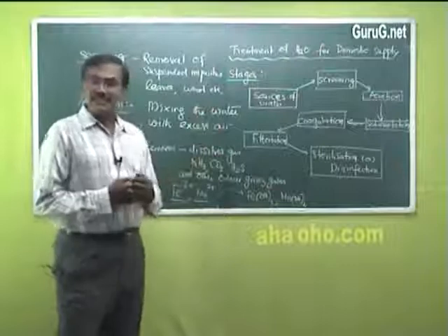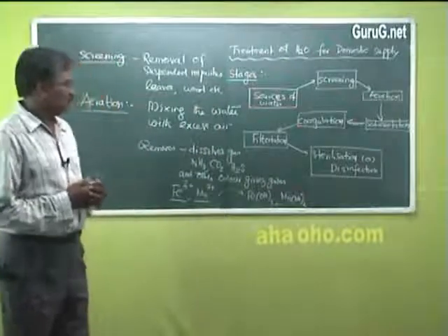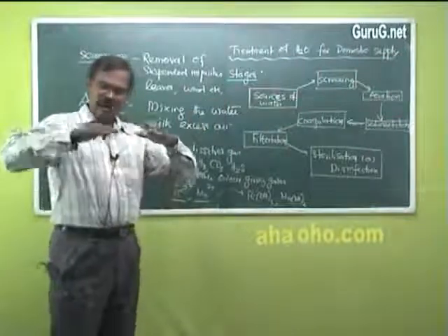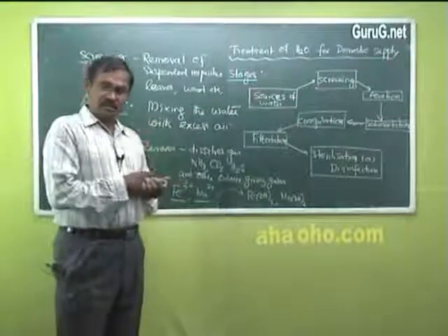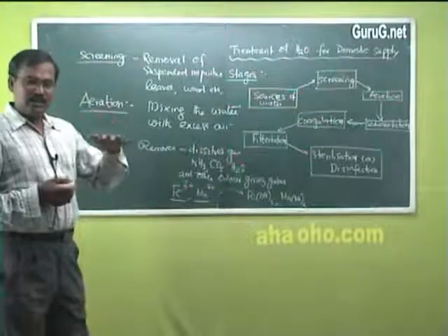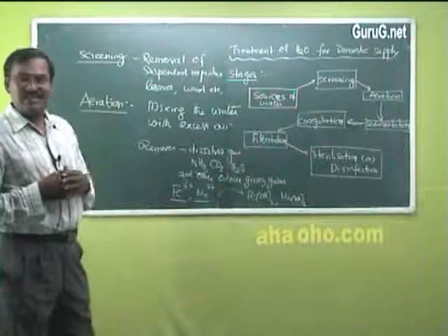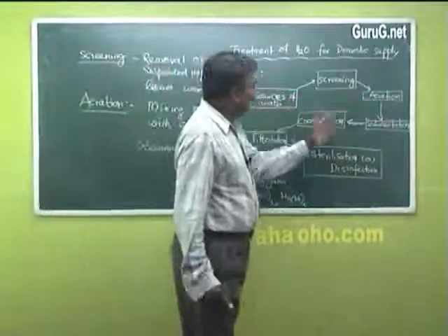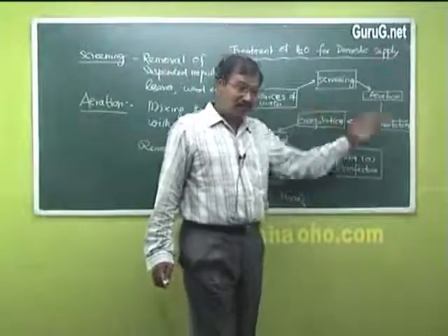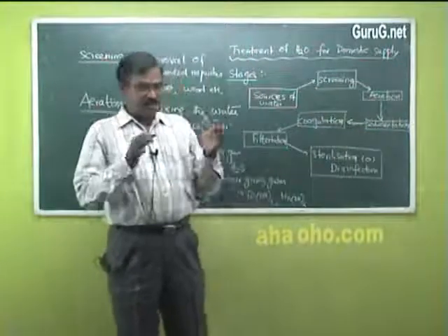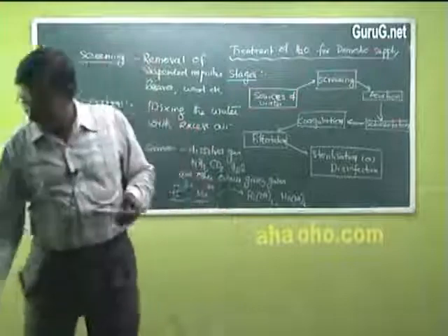So the next one is sedimentation. Sedimentation means we allow the water to settle down in a tank. When it is allowed to settle down, the particles settle down by gravity. Here we are not going for any mechanical means, and we are not adding any chemical in sedimentation. We are just allowing the water to remain in the tank.